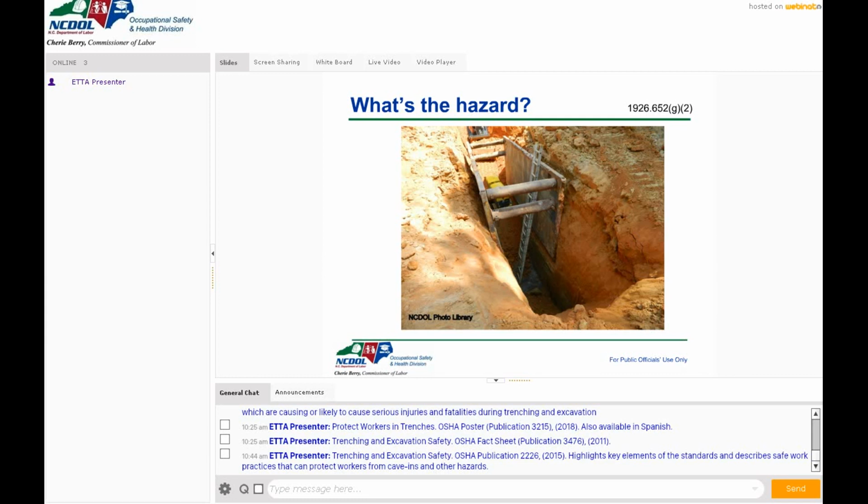Got the soil pile too close? Absolutely. That's a biggie. And yeah, Steve's got the trench box along the bottom. A lot of people don't catch that. You cannot be more than 2 feet off the bottom, because the soil may be heavy enough to collapse in around it. And that's a real good one.